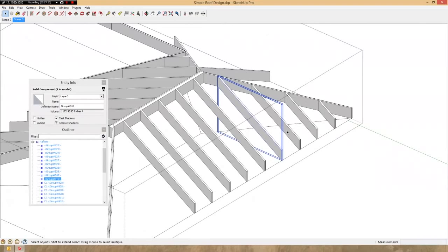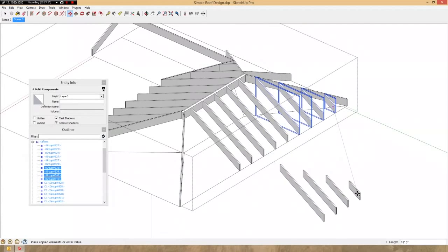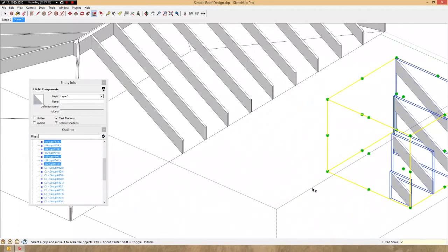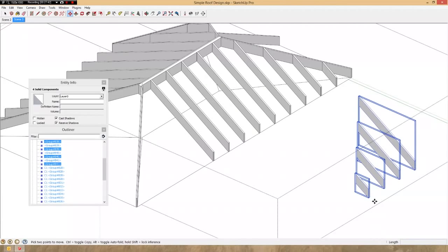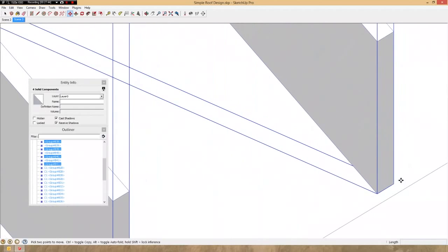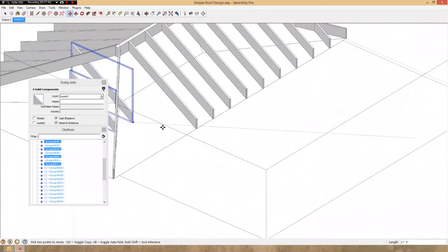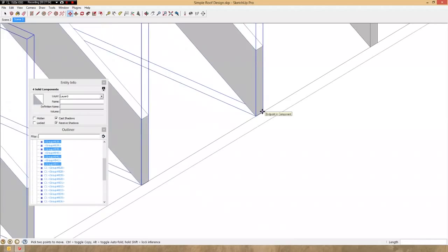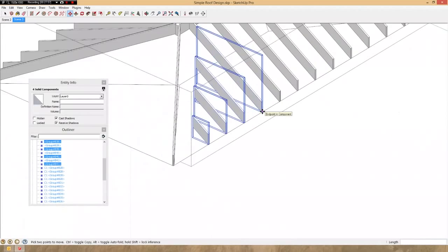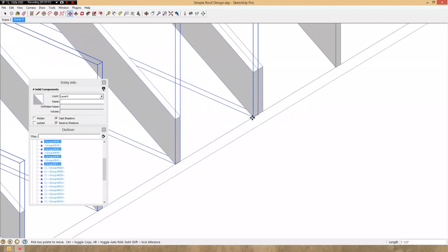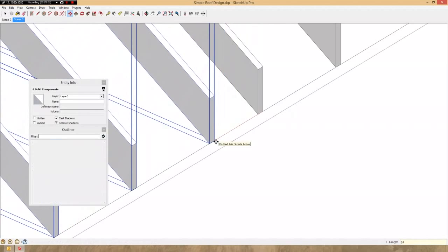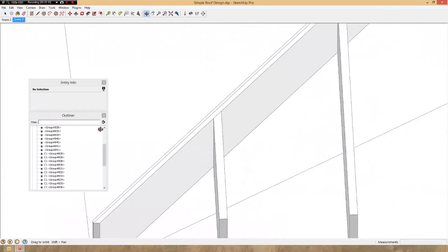Let's select these jacks and duplicate them, make them a mirror image. Copy, drag, S for scale tool, -1 to reverse, M, shortcut key for move tool, just locating there for convenience. And we would be moving along what axis here? The red axis. So I'm going to select and then move along the red axis. I could hit the right cursor key to lock on that axis, type in 24 for 24 inch spacing, and there we have it.